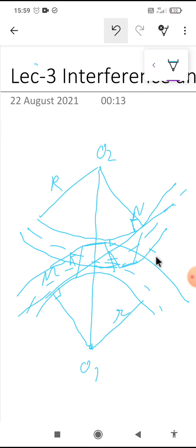So these are both addendum circles. Now what I'm saying is that if the radius of the addendum circle of the pinion is increased to O1N, this is the addendum circle of the pinion, and this I am writing as gear. So if the radius is increased to O1N, so if it is increased till here, that is the maximum addendum circle.